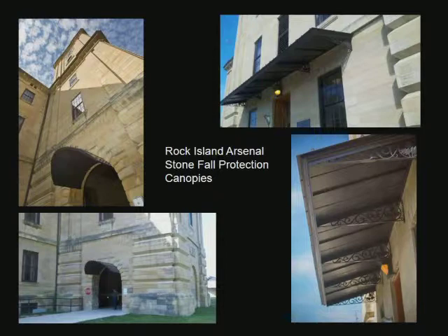Yeah, one more question here. Is there a product that you add to the FRP to help prevent from producing static in a Class 1 environment? Yes. Again, the typical ASTM corrosion laminate calls for a veil on the interior that holds 90% resin, and the next layers are chop strand mat that holds 70% resin.